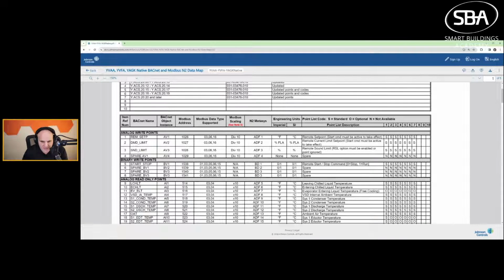And these sequences of operations in the specification and the MEP set should reflect the sequence of the chiller if you are using an integration. Here's where the challenge happens. You have a mechanical engineer who writes a completely different sequence, or you have a commissioning agent who comes along and adjusts the sequence. No longer can the unit perform that sequence because the sequence that they wrote is actually different than what the integrated sequence is.